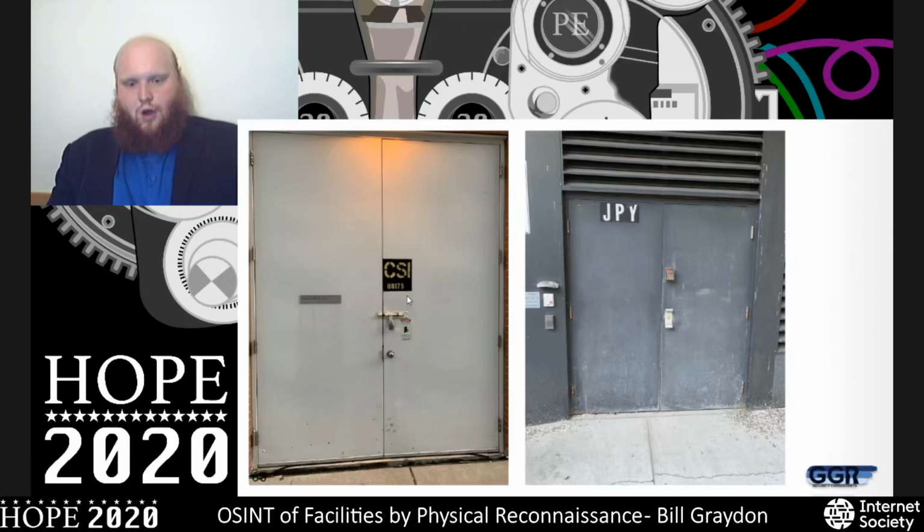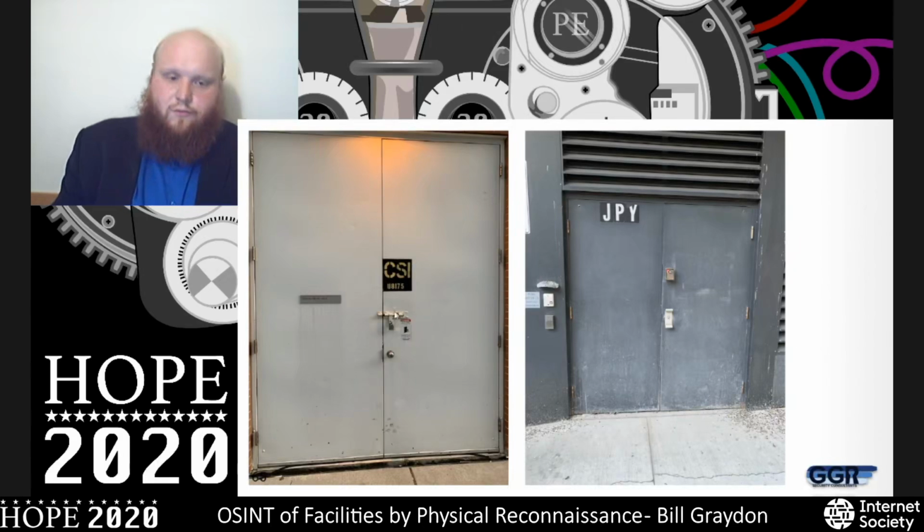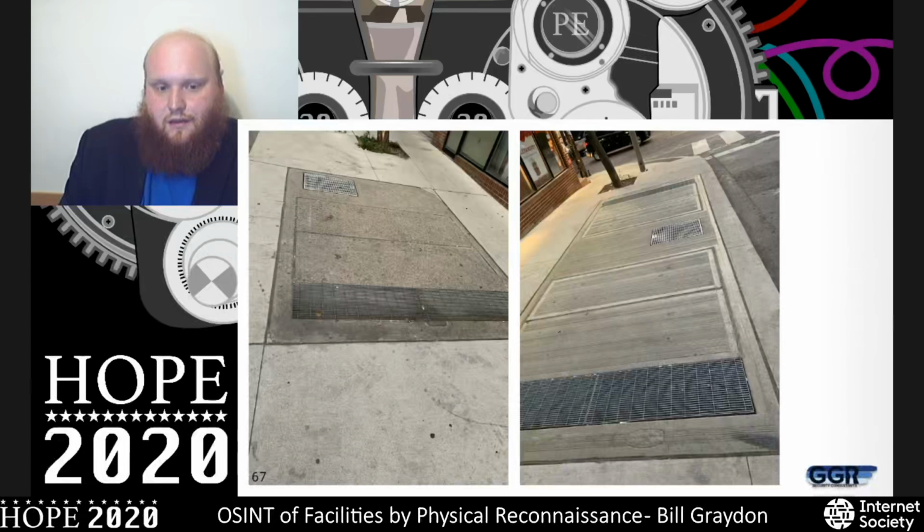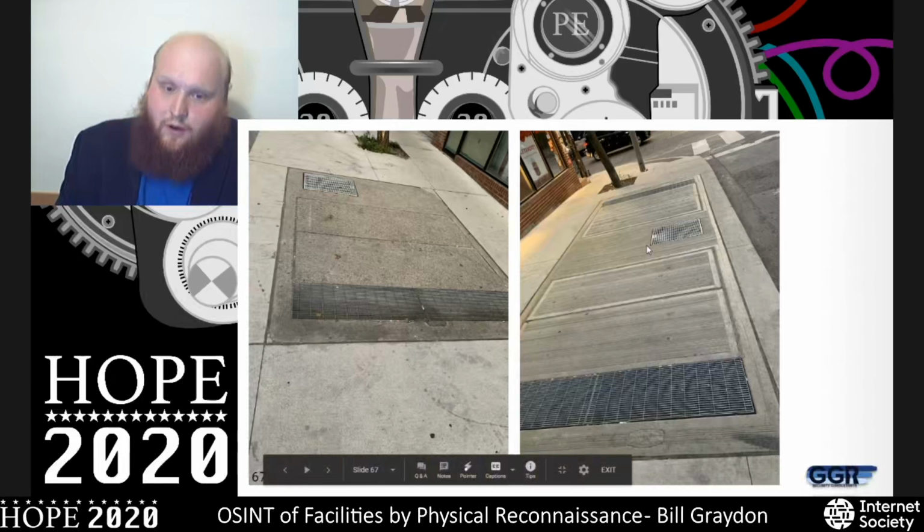We can also spot the incoming transformer room. So this is a grade level transformer vault. It has the power company's locks on it, as well as decals. We might have a pad mounted transformer exposed to the elements outside, and we can read directly off of that what make it is and what its capacity is. And we also might see these below ground transformer vaults here. They universally look like this. So now that you've seen this talk, you're going to start seeing these everywhere.